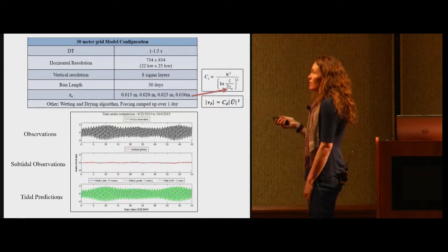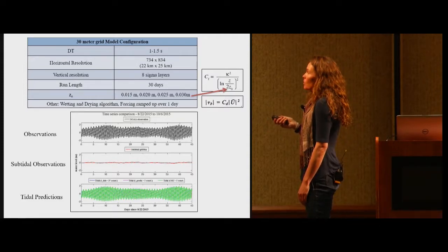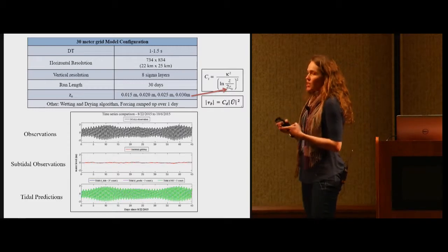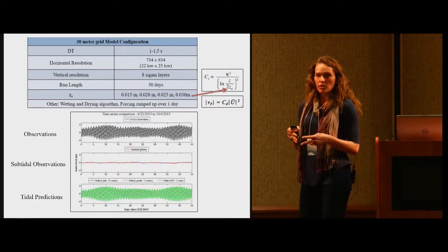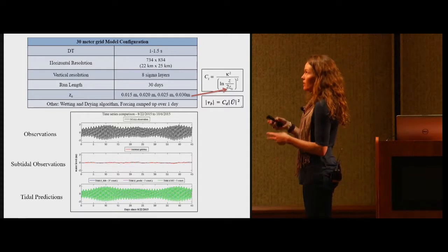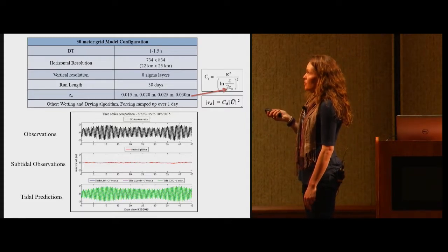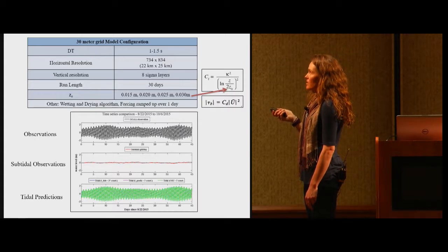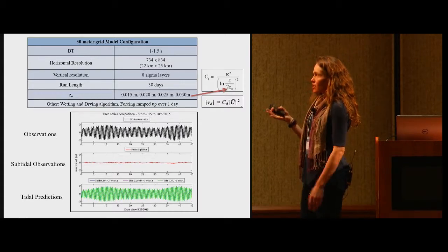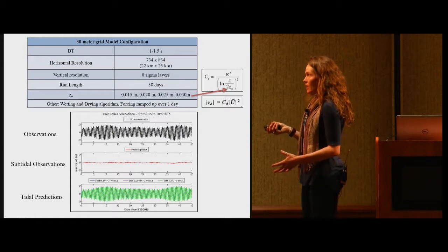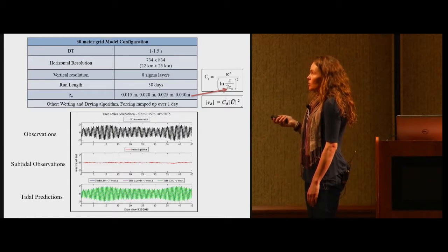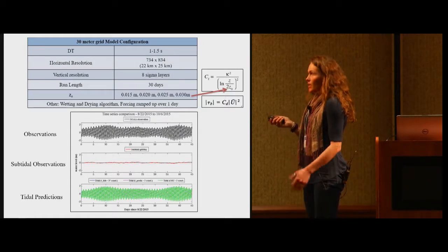So what we've done is we've run 4 different cases for both tides and including subtidal, which corresponds to meteorological forcing. And what this parameter does is it fits into this drag coefficient, which then gets put into this estimate for shear stress. I'll show that in a little bit more detail later. So essentially, we look at a tide gauge for our forcing in this model.